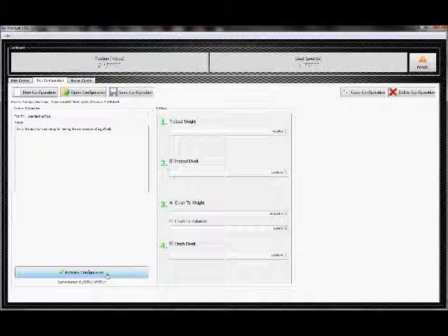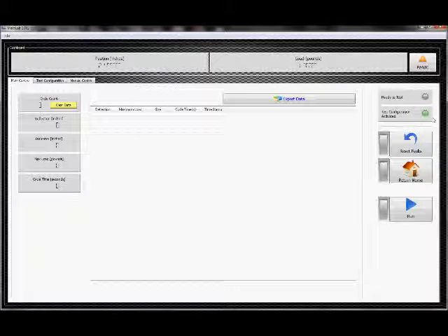So again, for good measure, I'm going to activate the configuration, and then we return to the main control tab. Now I have to go home before I can run a test, because in this case I'm near the home position. Nothing moved. It has been set as home. When I home it, it tares our load cell, which is to say it subtracts out the additional weight beyond 0 it has. Notice that our load cell is always bouncing. Every load cell has a minimum resolution. In this case, the one I'm using has a resolution of plus or minus half a pound.